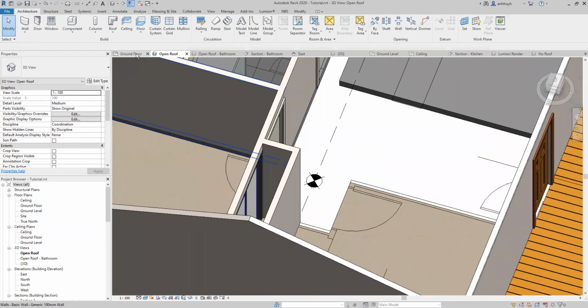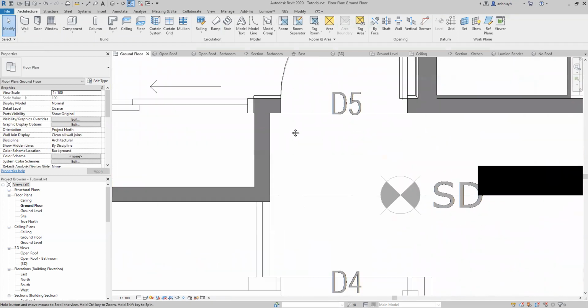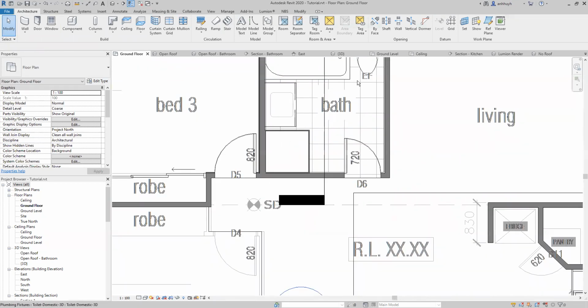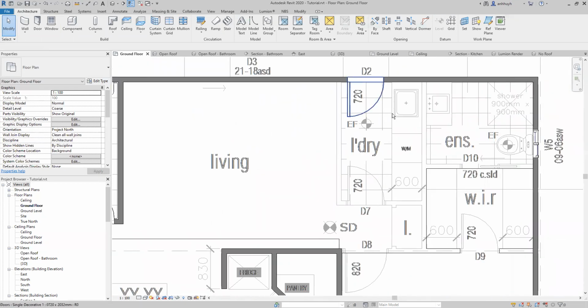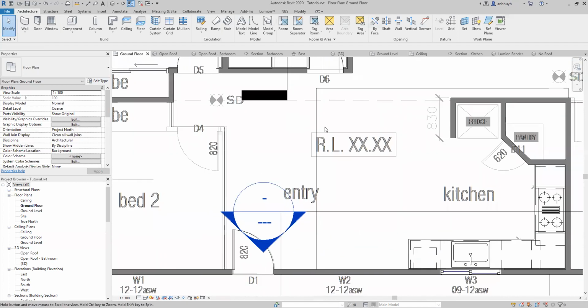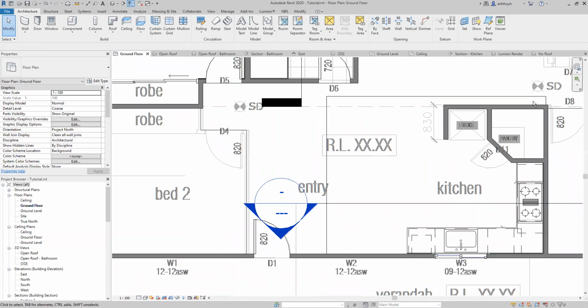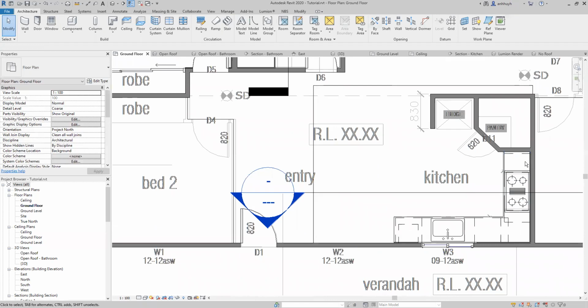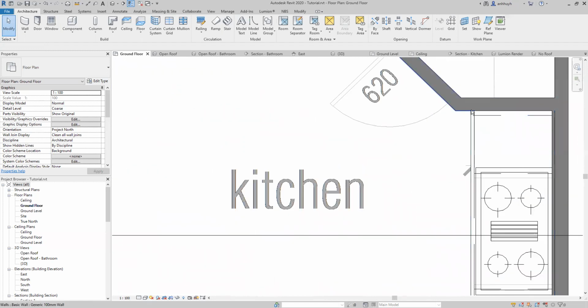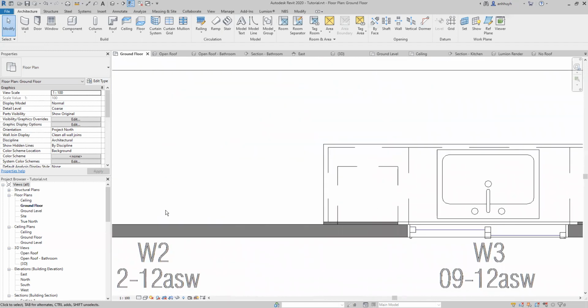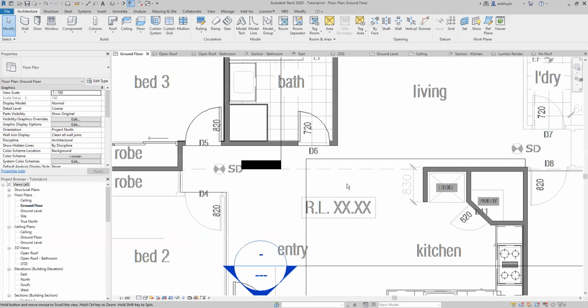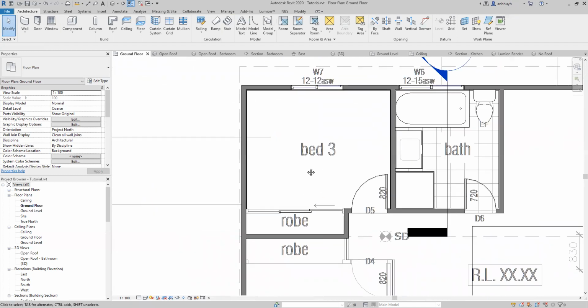So you will need to repeat this for all of your non-wet areas. So every wall other than the walls inside the bathroom, laundry, and ensuite will need to have skirting. Okay, so you'll have to trace the perimeter of all these walls here like that. Now, obviously, with these, for example, the kitchen, with the cabinets, you won't be able to see the railing behind them. So you can just stop at this point and then continue down here. All right, so that's the skirting.